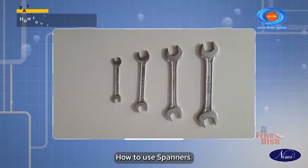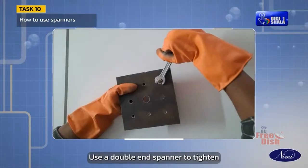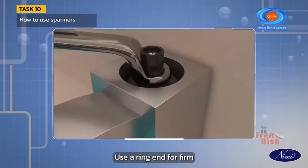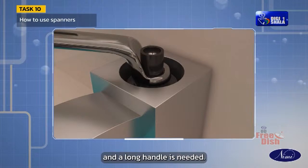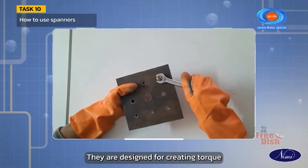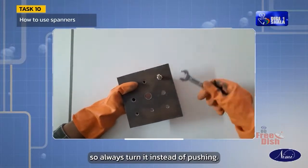How to use spanners. Select the correct size of the spanner for locking nuts. Use a single end for a specific purpose. Use a double end spanner to tighten two different sizes of nuts. Use a ring end for firm grip while tightening bolts and nuts where there is obstruction and a long handle is needed. Avoid pushing a spanner. They are designed for creating torque and not pushing. Pushing a wrench can break it, so always turn it instead of pushing.